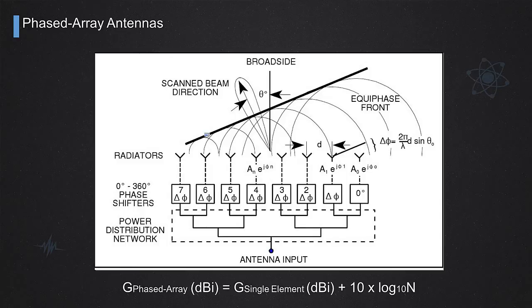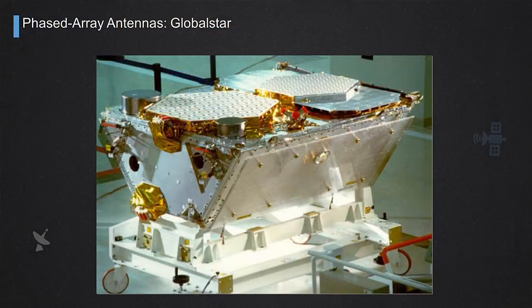So this is a simple formula to derive the gain of a phased array. Of course, there are several other considerations to be made, but this is a first approximation of the gain of an array antenna. Examples of direct radiating arrays: as a matter of fact, this example is an active antenna, but it is also a good example of direct radiating antenna.